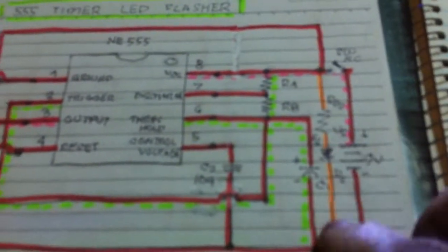So in this circuit, the red one, we can calculate the values of the protector resistor of the LED. We can calculate it using Kirchhoff's voltage law, and also here. It's the same formula here. Kirchhoff's voltage law, voltage supply, voltage drop. So we got 350 or 500 ohms. So I'm using 500 ohms for these two resistors to protect the LED.